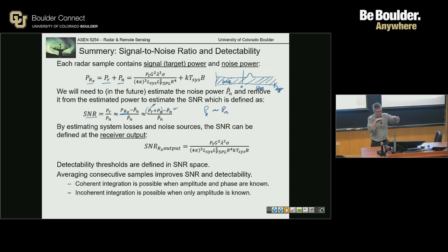Take an FFT of this power, you'll get the power distributed. If you had a constant of 5 at every single time step, take the FFT, it's not varying in time, it is DC. It's non-varying. It will have some magnitude based on the number of points times that. And so that will have a DC component. There's no variation. And it would be here.